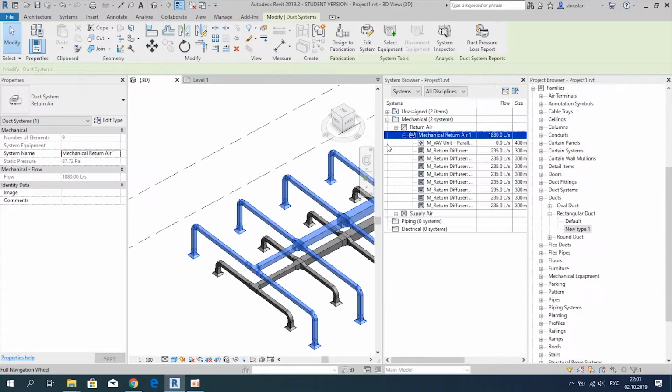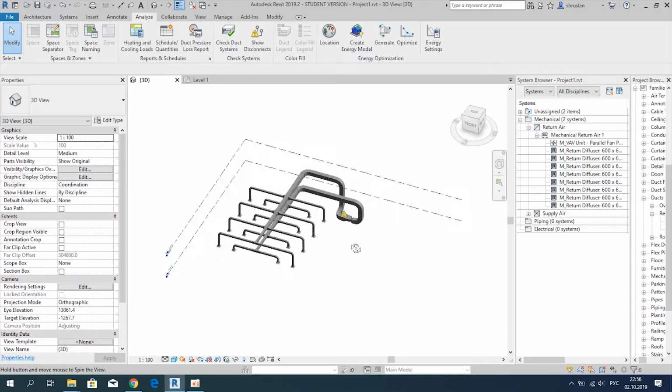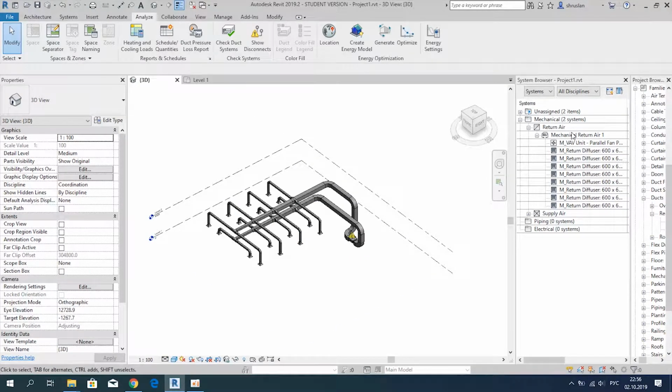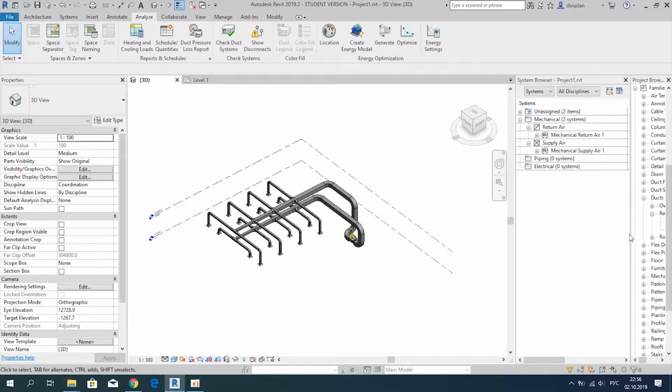The connectors have several parameters for sizing: air pressure and air flow. Based on this, the duct sector takes it and sets the cross-section after the function call. We can do sizing for a separate duct sector and for the whole line too. It is an important fact that sizing depends on the right settings in the family connectors.